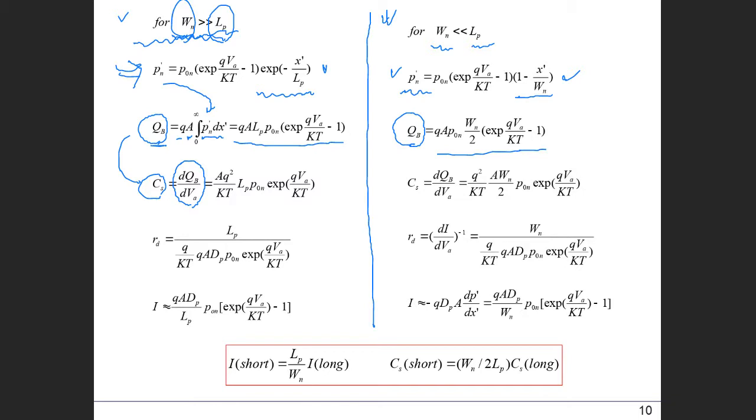That is basically the definition. If we use the obtained QB and apply the derivative with respect to VA, we get this kind of expression for CS. The same way, for this side, we get this one.